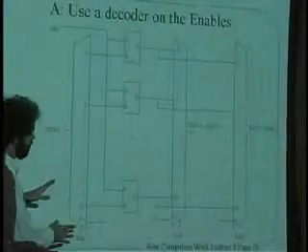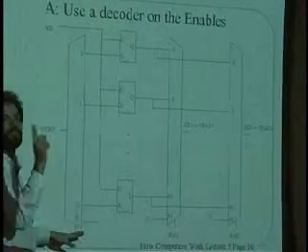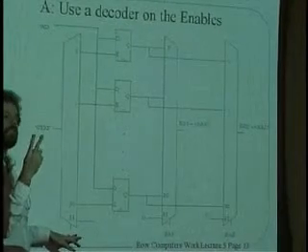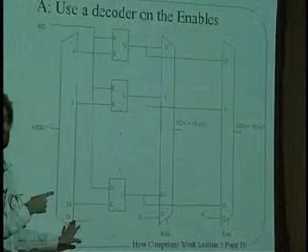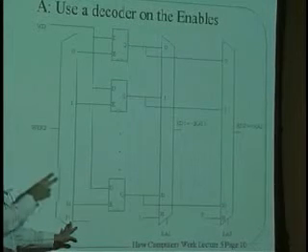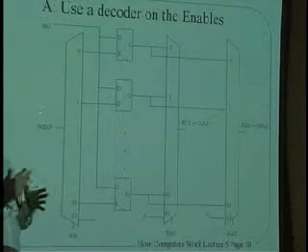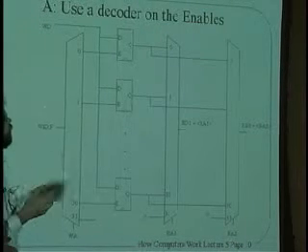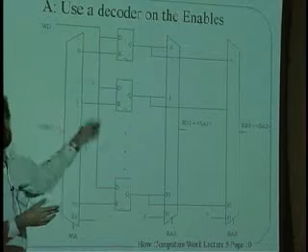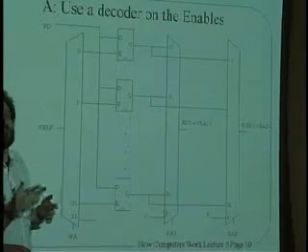You're absolutely right. Part of the idea here is to minimize the number of wires that are going to control the box here. So in other words, we need 5 bits to specify 1 register to write to. If we had 2 registers to write to, we'd need 5 bits for one of them and another 5 bits for a second one. Or we'd need a separate one of these E lines for each of the registers, so maybe we'd want to write to more than 1.